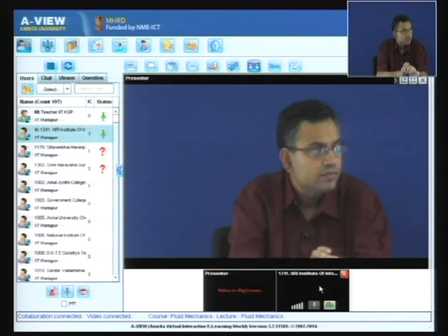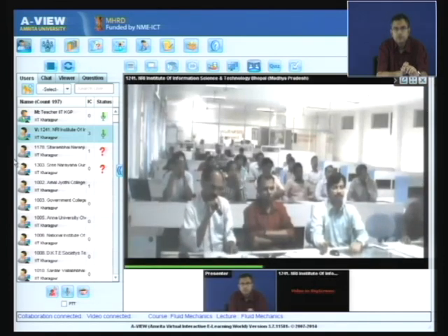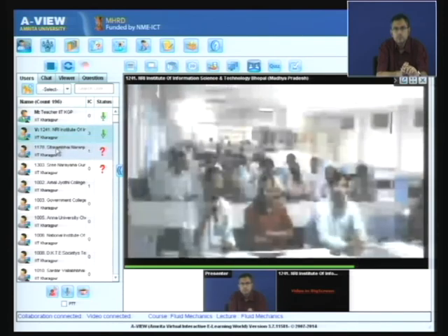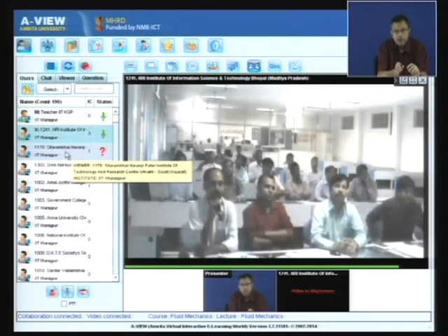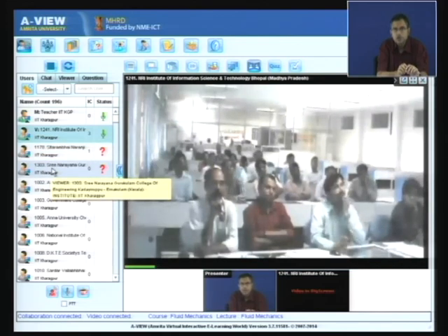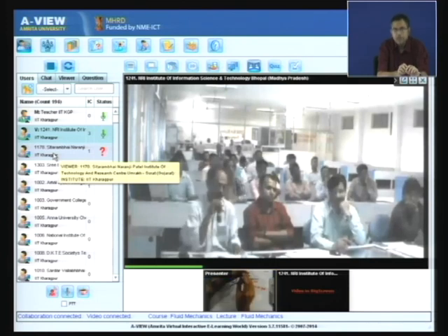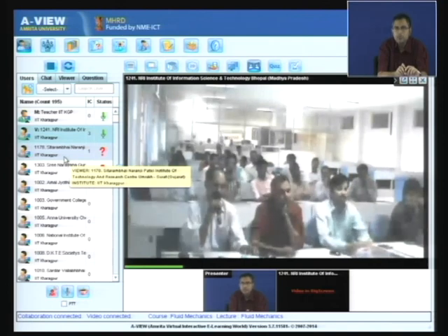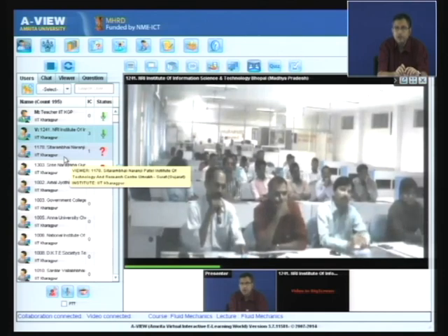Good afternoon, sir. My question is, what are the different factors affecting boundary layer conditions and boundary layer separation? Is this a physical concept or a hypothetical concept? Boundary layer separation depends on several things. First of all, what is the pressure gradient that you are applying. A necessary condition for boundary layer separation is that the pressure gradient must be adverse, but how adverse it is depends on the particular flow configuration.